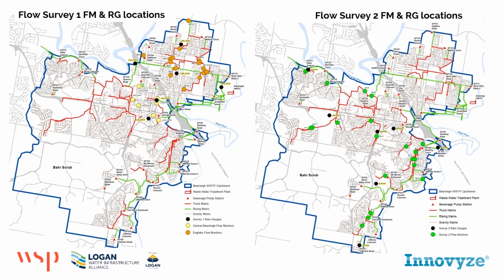So, it ended up covering a 6-month period, and there wasn't overlap between the flow surveys. So it does create a few challenges in the modelling space. The main thing there is if you can get all your flow monitors in the ground and conduct a flow survey over a common period, that is certainly ideal. One of the challenges with Australia is that we have a highly variable climate. So in this particular year, it didn't rain a lot in the first half of the year. And our wet season typically spans from about December through to March or April.